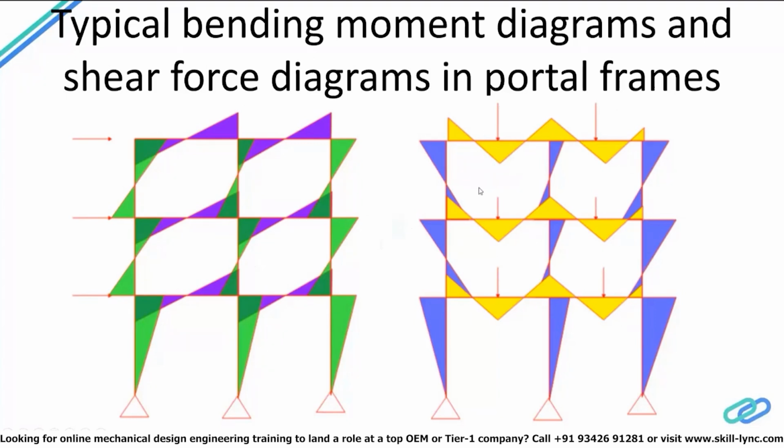In reality, when we design these structures, we have different load combinations based on the different design codes. So we combine the left diagram with the right diagram based on different load factors. Say it's a dead load plus wind load, and the load combination is 1.5 wind. In that case we superimpose this bending moment diagram scaled up by a 1.5 factor with this bending moment diagram here, and come up with the maximum demand that any beam sees at any section.